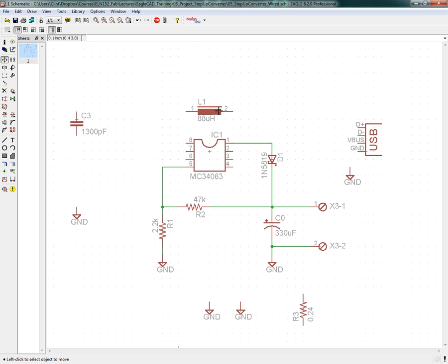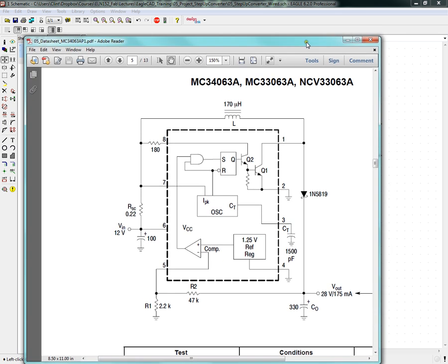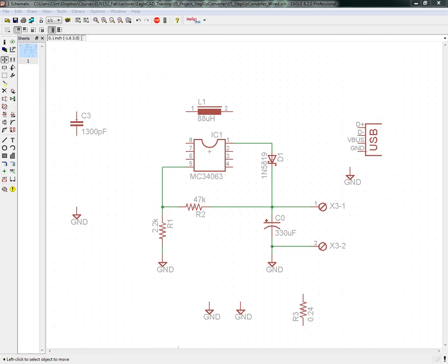Now notice that this symbol for an inductor is the European symbol. The European symbol is just a rectangle that's filled in. For European symbols, a rectangle that's empty in the middle is for a resistor, and a filled in one is for an inductor. And if you have a line there, it just means that there's like a steel or a ferrite inside of it. So this is the American symbol. So you'll see either American or European symbols, and it's okay to have either one of those.